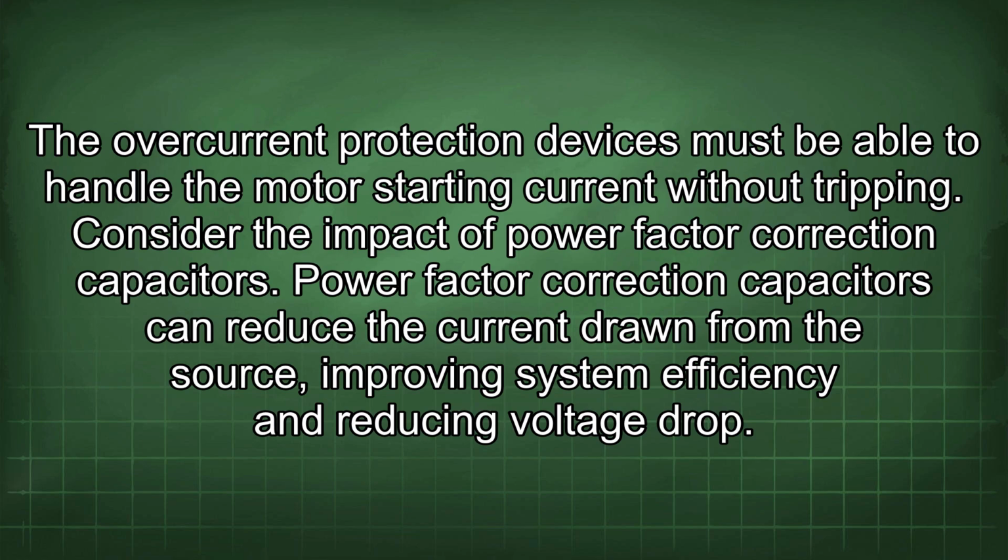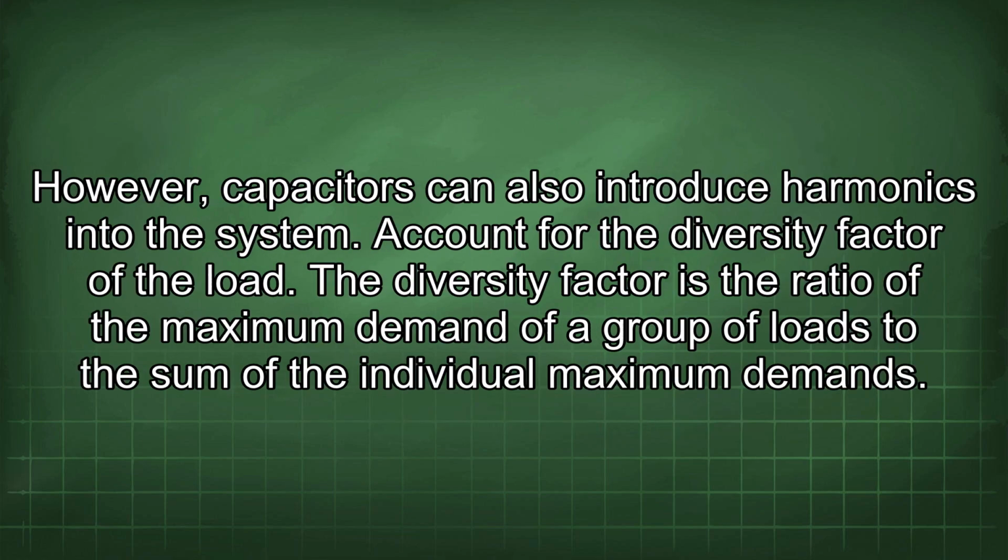Consider the impact of power factor correction capacitors. Power factor correction capacitors can reduce the current drawn from the source, improving system efficiency and reducing voltage drop. However, capacitors can also introduce harmonics into the system.